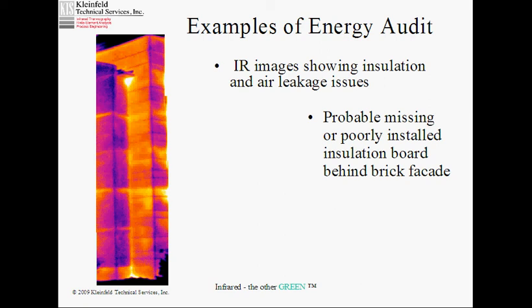The possible exception, but probably not, is that very hot area right up at the top there in the inside corner. Inside corners are protected, so they're radiating at each other, so they're not radiating to the world as much, so they're not cooling off that way as much. They are also protected from wind currents, so you will tend to see greater warmth in a protected area. So you'd expect a little more warmth on the inside corner and more beyond that in the three-way corner. That looks extreme.